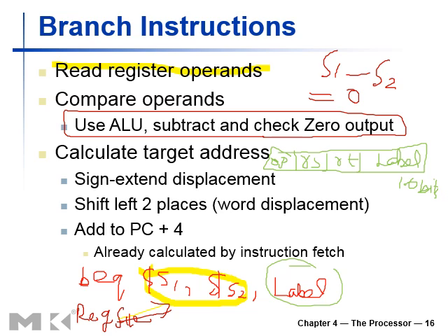So we're going to sign extend that, and then we have to multiply by 4. So we have to use shift left 2. Why do we multiply by 4 with it? Because if you remember, the next instruction address, or the address of the memory location, we have to multiply that by 4 in order to generate the physical address or the correct address. So by left shifting the data by the quantity of 2, we multiply by 4. If you have to multiply the data by 4, we have to provide 2 left shifts.